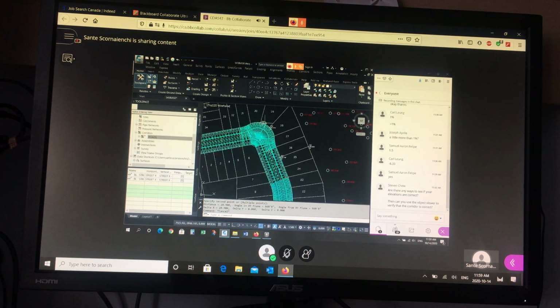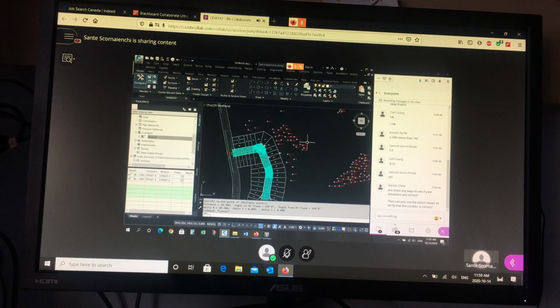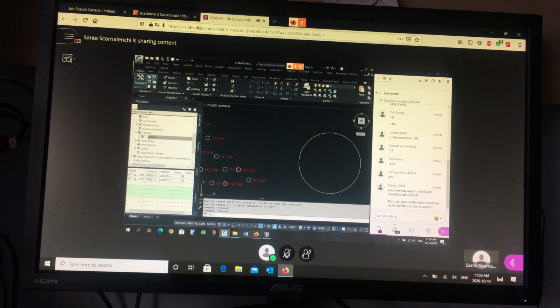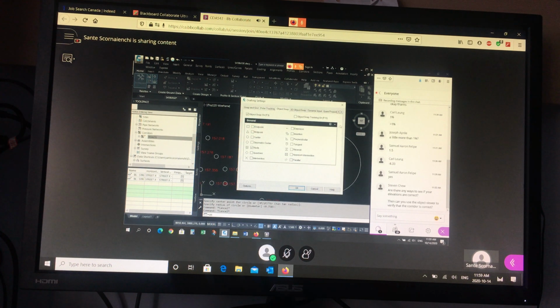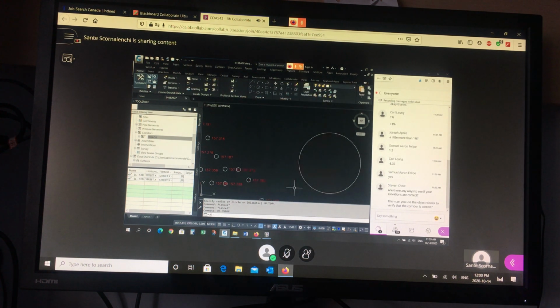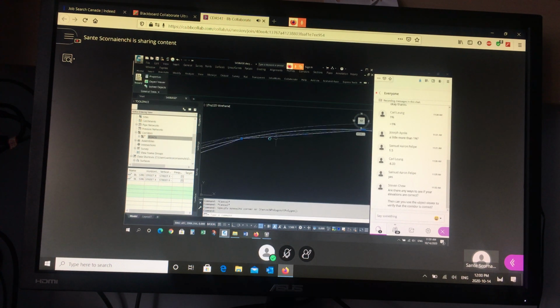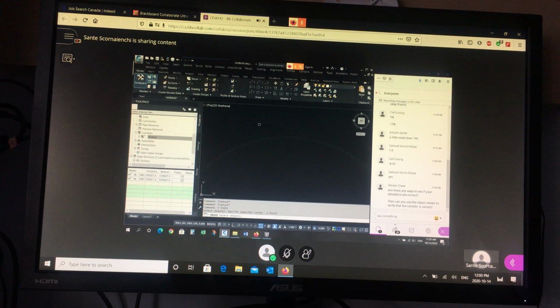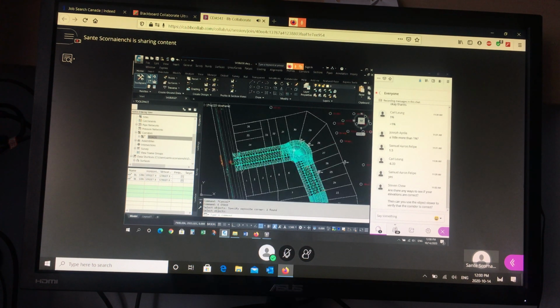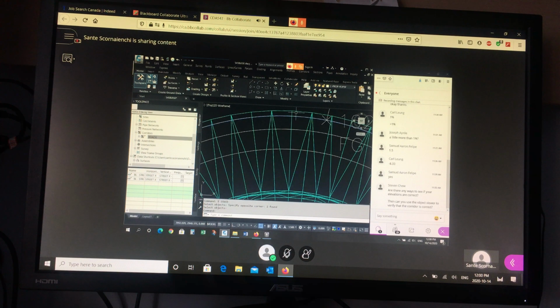Every time you're going around the curve on the outside, if you draw an arc, if you draw a circle, if you want to approximate that with straight lines, if I want to draw a polyline to approximate that, that looks like a curve at a glance, but if you zoom in, the circle is always beyond the edge of the straight line, so anything out here would be off the limit of the surface. So it's always on the outside turn that you have a problem. So just make the boulevard wider so that you don't stop at the street line, you go a little bit beyond.